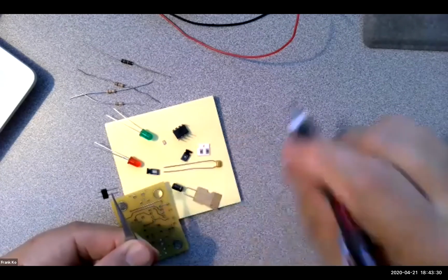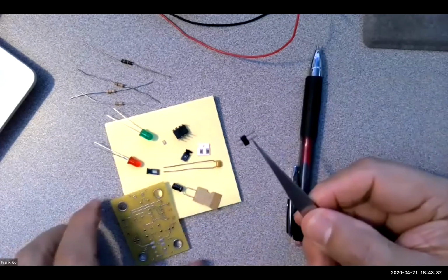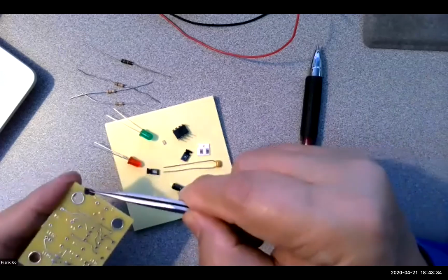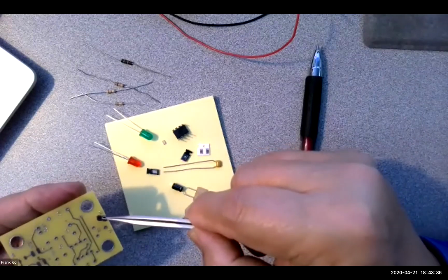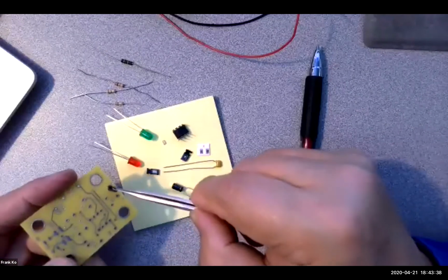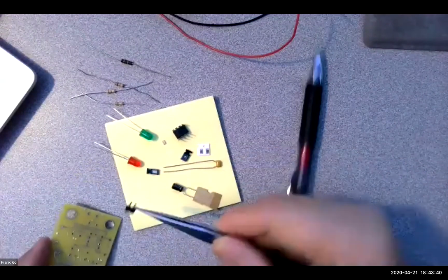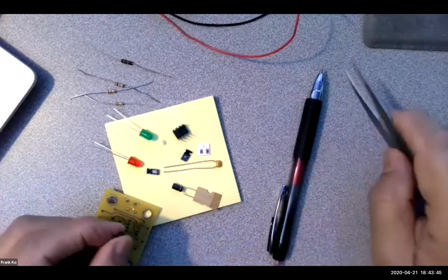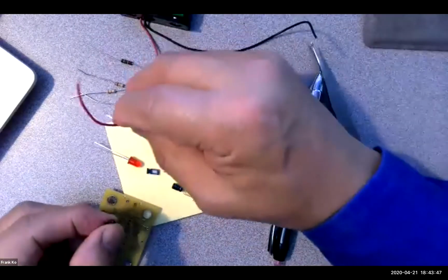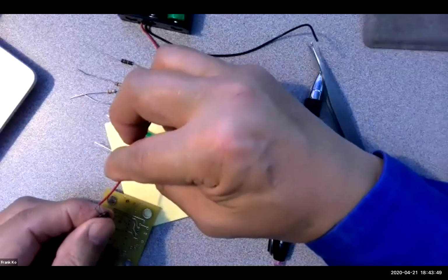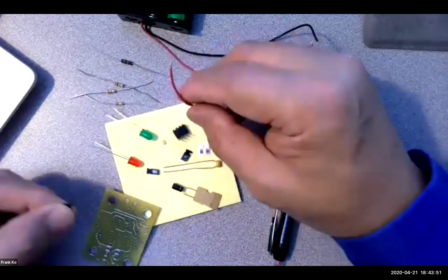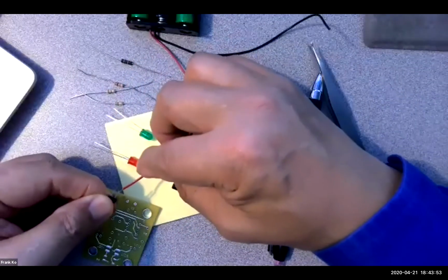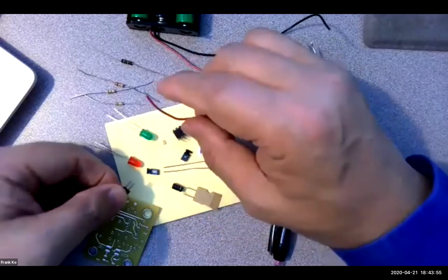Okay, so then you'll have 2 of these pieces, and then you will have one end go here. Put the short end in with the long end up, so that the long end will be sticking up off the board, and you'll be making your connections with voltage using your battery leads onto the jumpers J1 and J2, okay?